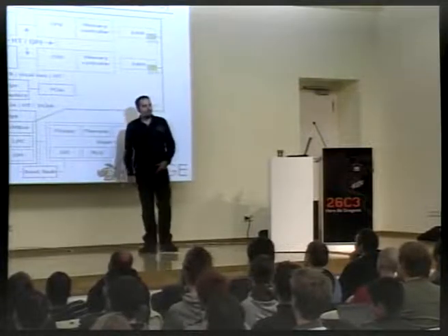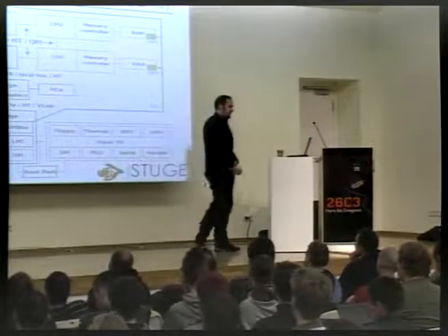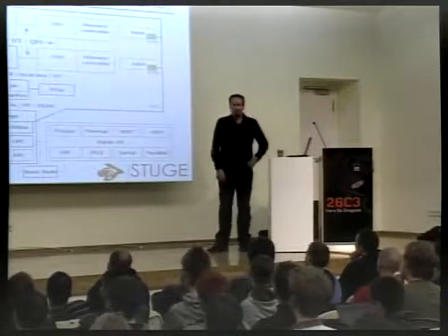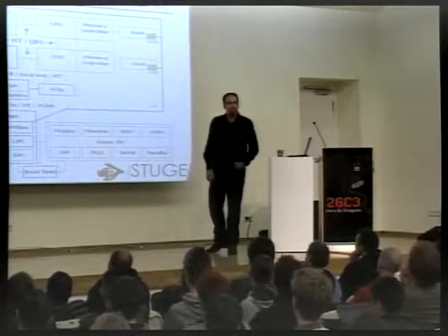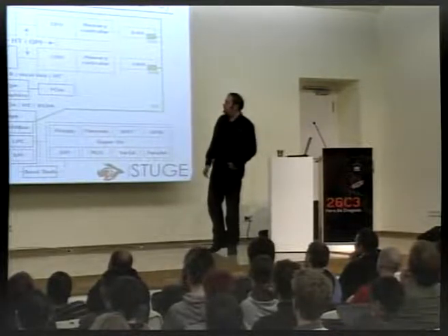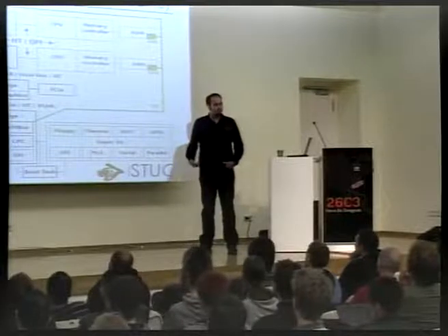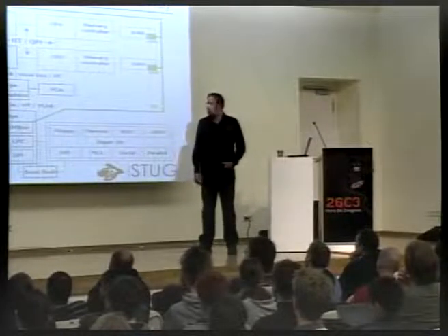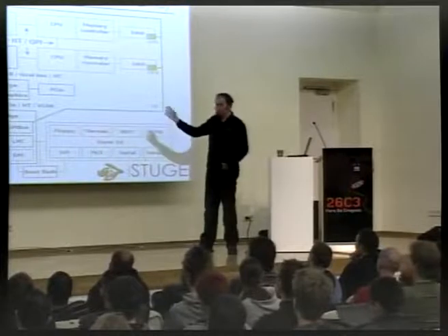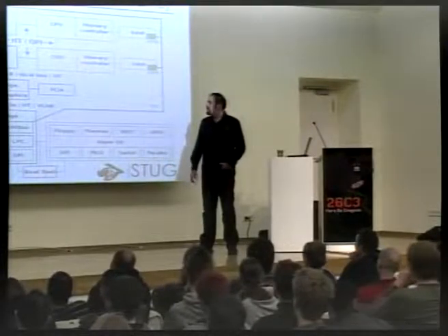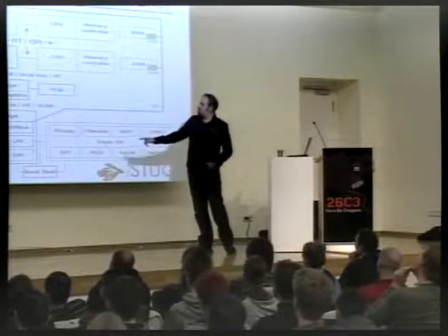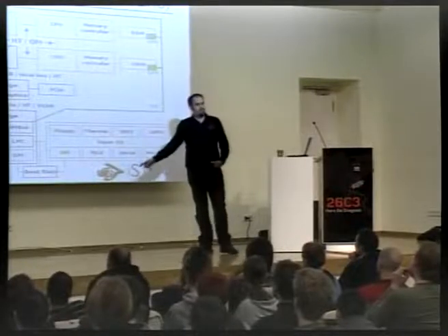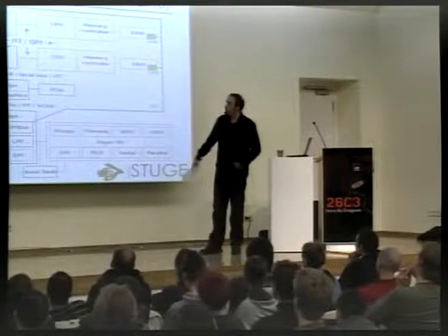That's the flash chip where we have the firmware stored. Remember in the 1980s picture, we had a boot ROM up there. It was connected directly to the CPU. But nowadays, it's a little bit further away. However, it's still accessible when the system powers up. The CPU fetches the first instruction when starting to execute. So when all these components come out of reset, they will be set up so that when the CPU accesses the special magic reset vector address, top of 4 gigs, it's going to be decoded to the boot flash chip down there, and all the components along the way have to play along.